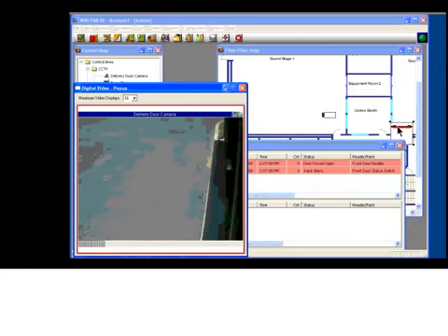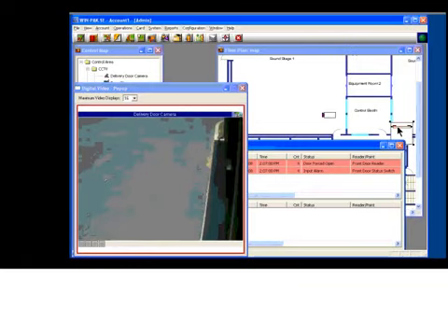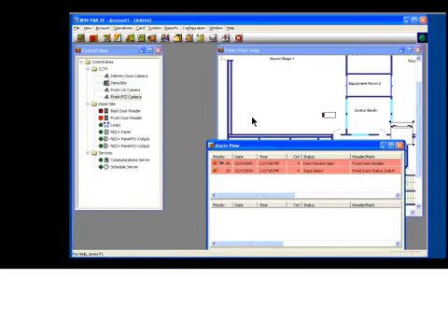So once somebody forces a door open, you've got a camera that pops up. When that camera pops up, we've got the ability to see the alarm. Now again, without using integration, yes, we can use relays to tie all this together. However, the advantage of using integration is that if the security officer is not sitting in front of his desk and doesn't see the event when it occurred, one of the advantages that the security officer has